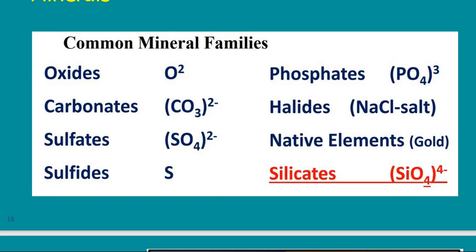It has no chemical reaction. Because sand usually is either carbonates or silicates. There may be other things, but it is not important for me. What I care about is to differentiate. I want to check, is there carbonate or not? So if I put HCl and there is a reaction, it means carbonates: reject. No reaction means silicates: accept. That's all.